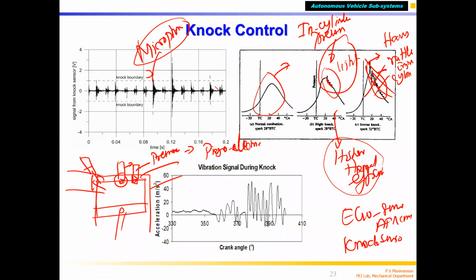Pressure sensor, correct? We know that the pressure can go up to 70 to 80 bar. Diesel engines can go higher also, correct? So depending on petrol and so on, the sensor measures what the pressure is. As the piston is going up, the pressure increases. You give a spark here, combustion happens, and it reaches what is called peak pressure.